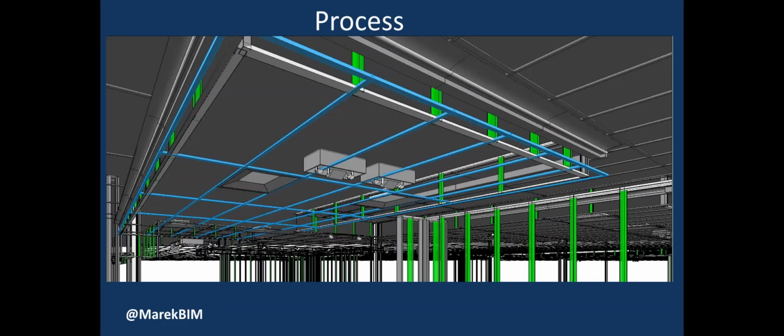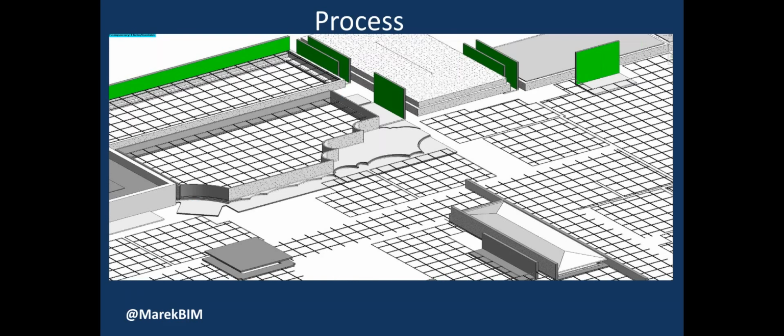Ceiling grid, acoustical ceilings. We use actual grid in most of it. We'll drop in the libraries from the manufacturer. This makes it a much better process than just the normal 4-inch space that we'll put in there to save space. We like to actually drop our grid in, as it helps with the clash detection.